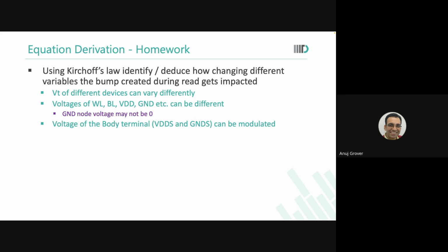What this will do is give you all the levers that you can play with. You could play with VBL to reduce Vx. You know that? If you want to reduce Vx, if the VBL is lower than VDD, then the potential divider is between VBL and 0 instead of VDD and 0. So Vx will reduce automatically. Noise margin will improve. Are you with me?